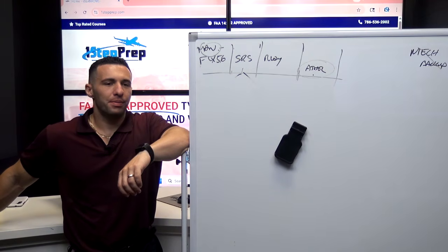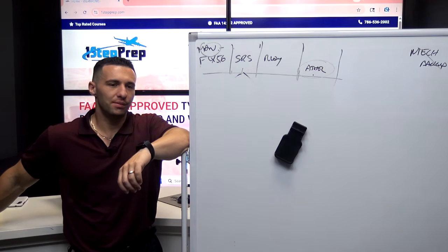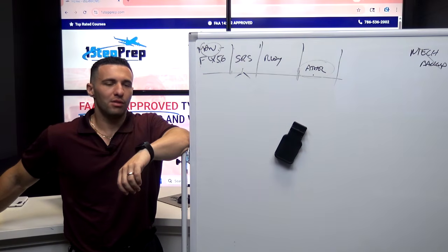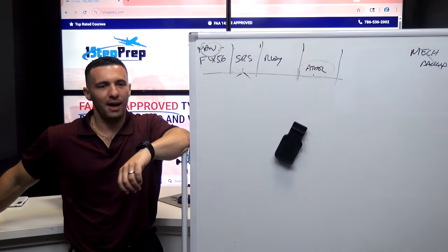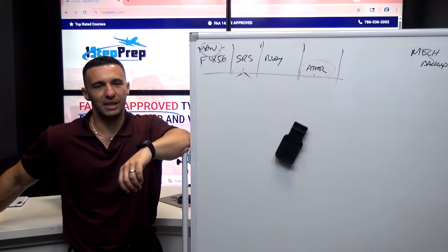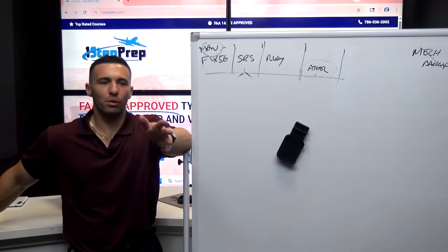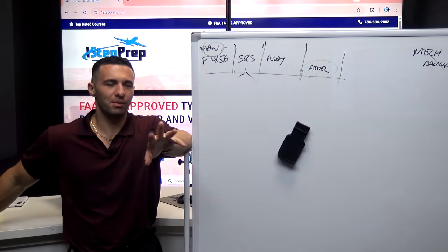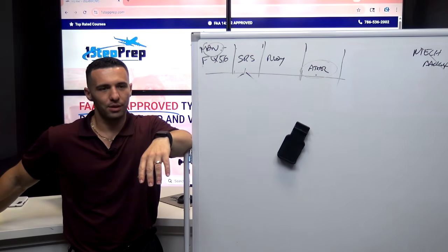Is the VAP to VAP plus 10 also the command the SRS gives you in a Windshear situation? So the initial pitch attitude is 17.5 in a Windshear, 17.5. That is the pitch attitude initially, and then as needed to not have a radio altitude decreasing. And so let's talk about Windshear for just a second.